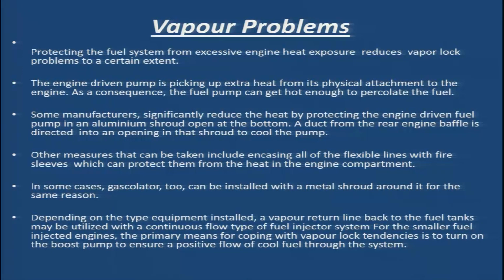Some manufacturers significantly reduce the heat by protecting the engine driven fuel pump in an aluminum shroud open at the bottom. A duct from the rear engine baffle is directed into an opening in that shroud to cool the pump. Different manufacturers adopt different measures to protect the engine driven fuel pump from absorbing heat from its surroundings. Other measures include encasing all of the flexible lines with fire sleeves, which can protect them from the heat in the engine compartment.